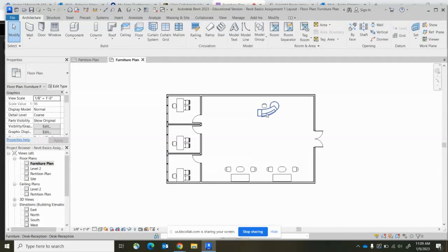The next thing we're going to look at is tagging your furniture. So Revit is often used for larger plans, commercial plans, where you will tag all of the furniture pieces, and then that coordinates back to a furniture schedule. For a residential plan, you may tag the furniture, you may not. It just depends on how your workflow or the design firm's workflow is for that.